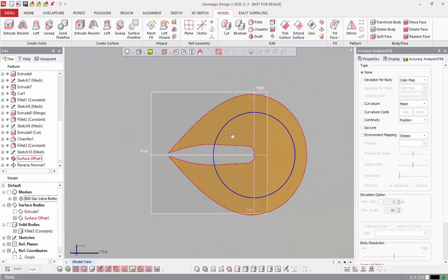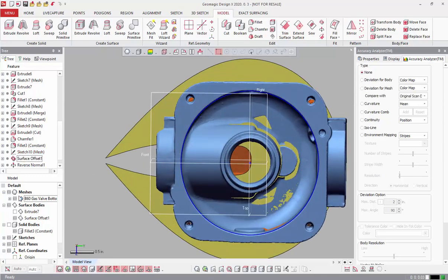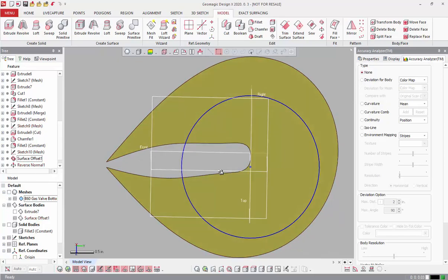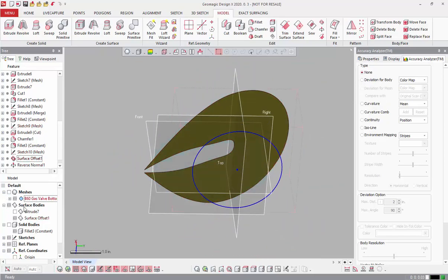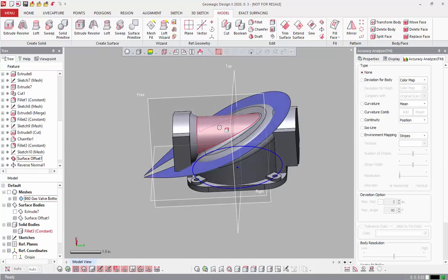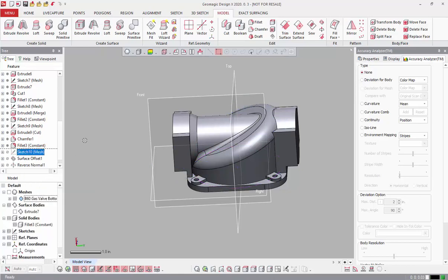So instead of doing this right now, what I'm going to do is move this surface offset up in the feature tree before that. Let's see, what is it that's cutting into that, like this cylinder or whatever was built, so that I just have a single surface here. And I don't know where that is, so I'm just going to roll back through my history tree and see how I built the beginning portion of the model here.